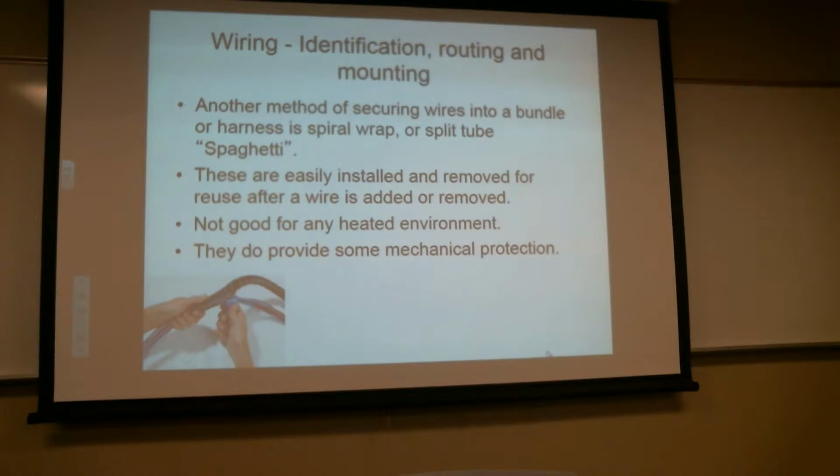And there's also varying degrees of heat shrink, some that can handle temperature well. Some of the better quality heat shrink not only shrinks and clamps things down, but it bonds itself to the wire and seals. They also have heat shrink connectors that have the solder inside the heat shrink. You just take the two wires and stick them in there, heat the whole thing up, the solder melts, fuses the wires together, shrink comes down, collapses around the wire, and seals it. It's as if the wire was never broken in the first place. However, it has been broken, and even using that really nifty automatic shrinking thing, you're only allowed one break in the wire.